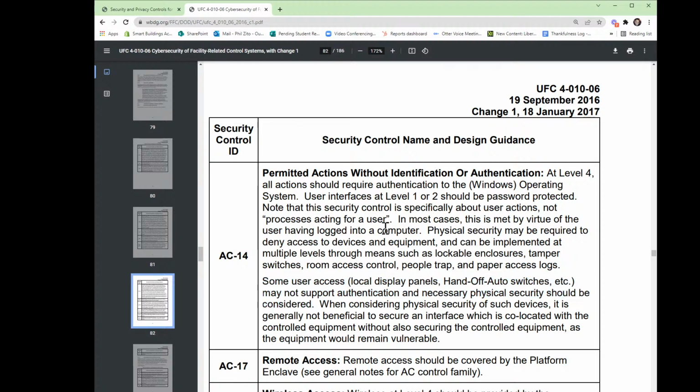So what are they saying here? Well, this is saying two things. Number one thing it's saying is, when you go to the BAS, to the server, to the web user interface, you should not be able to have access to things that are outside of your role, and whatever is outside of your role should require authentication, meaning login and users. This is why I said earlier, if you have unique usernames, you have strong passwords, and I'll add a third thing, you have unique roles, and the roles have specific access to only the things they need to access, you're going to make your system more secure. And that's basically what this is saying. So maybe you have a user role, an engineer role, and then a power user administrator role. And these different roles will have different access to different capabilities.